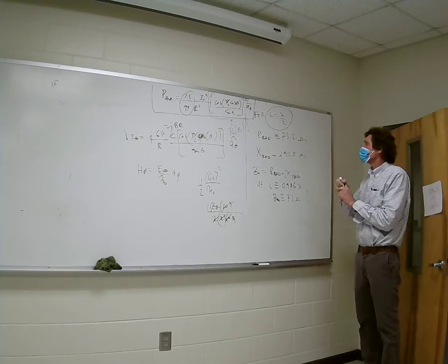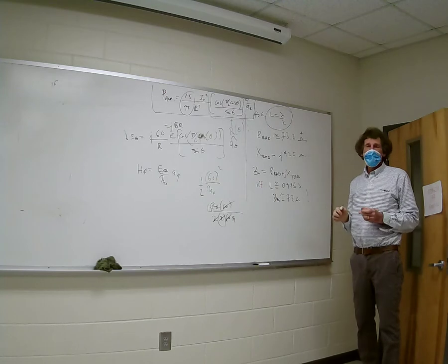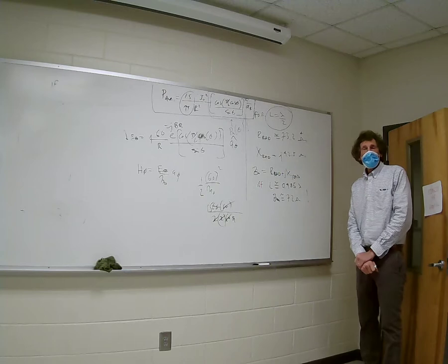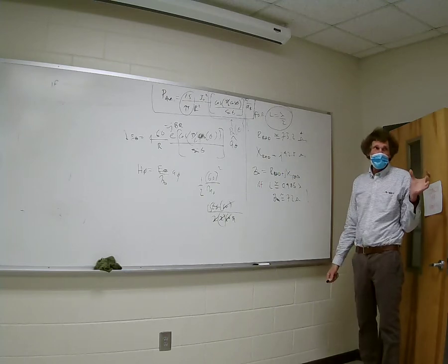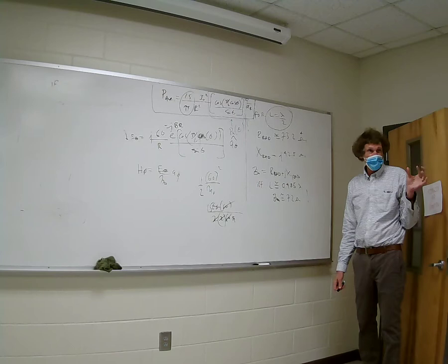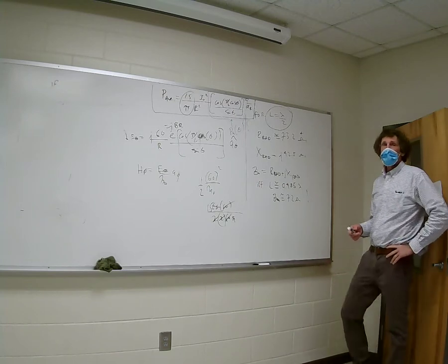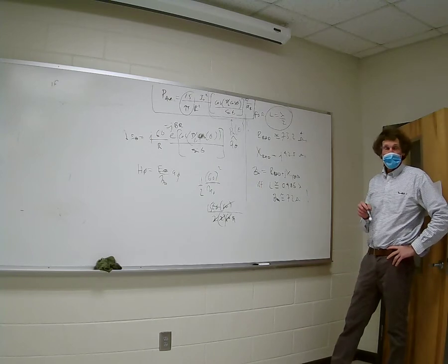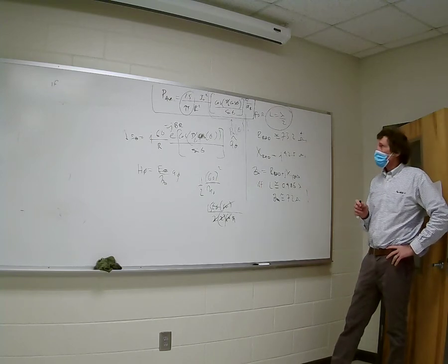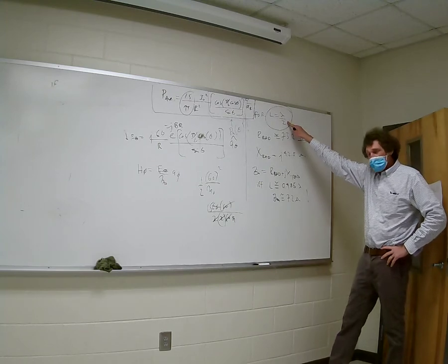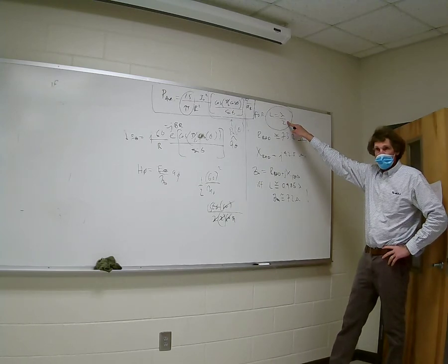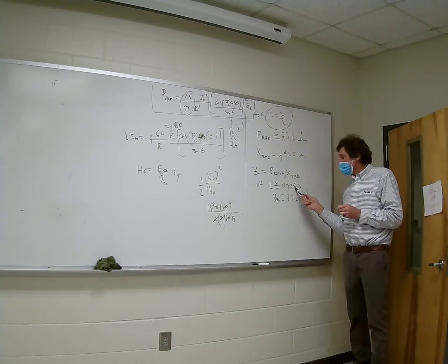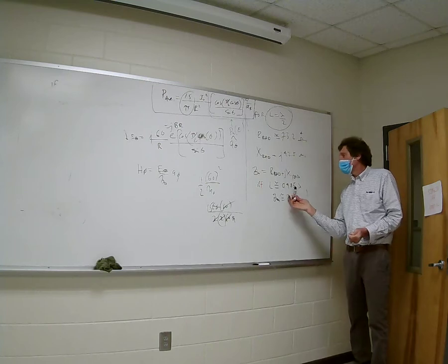This isn't really true. This will vary, 70 ohms, 69 ohms, up to about 74, depending on the length. If it's exactly halfway, it depends on the radius of the wire, all right? So it varies a little bit. Now here's what's always done, 99.999% of the time. Listen. In his book, he mentions it. They don't use a dipole that's exactly lambda over 2, which would be 0.5 length. They cut it down, so the total length is about 0.48. In his book, he'll have 0.485 length.